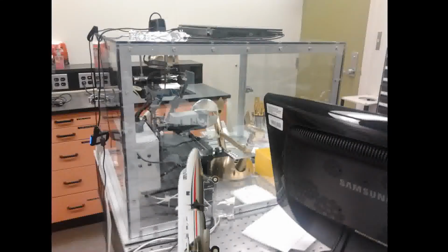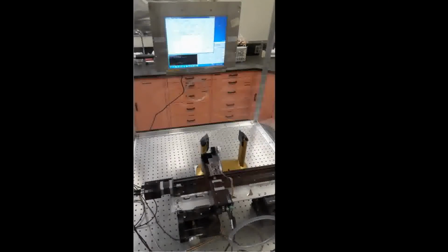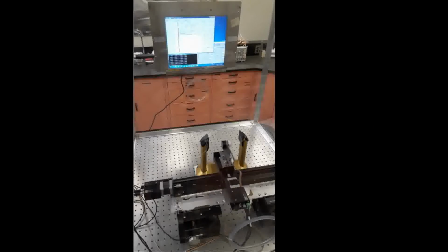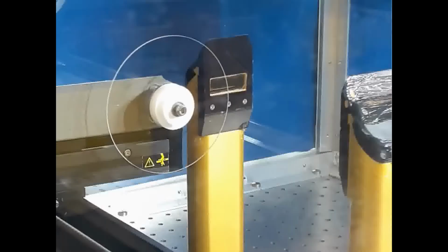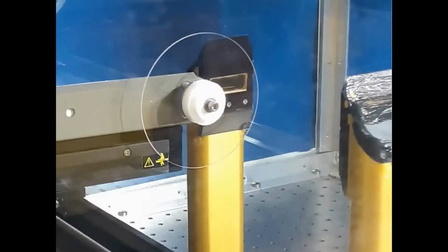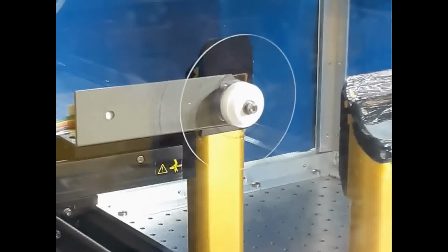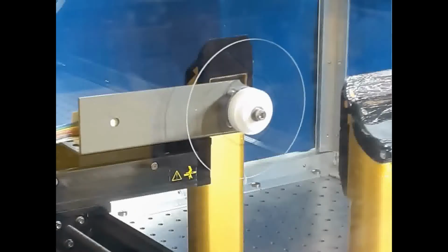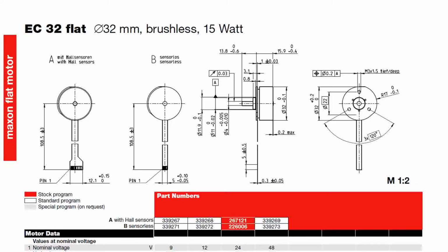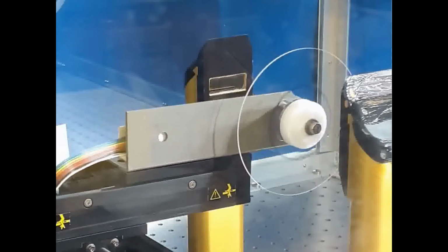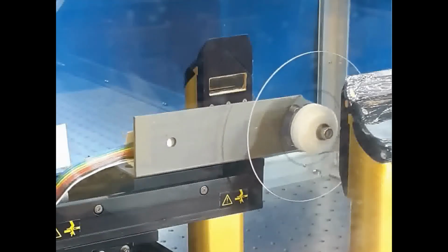For imaging probes, we have a spinning disc mounted on a computer-controlled XY stage. A glass disc with mono-sized, monospaced targets is moved in, ideally, the entire sample volume of the imaging probe: X, Y, and Z. A set of 26 different sizes of dots, on 8 discs, is recorded on each probe. The speed of the motor was limited because a flat motor was chosen for geometry considerations. This limited the tangential speed of the targets to about 12 meters per second for the entire set of discs.